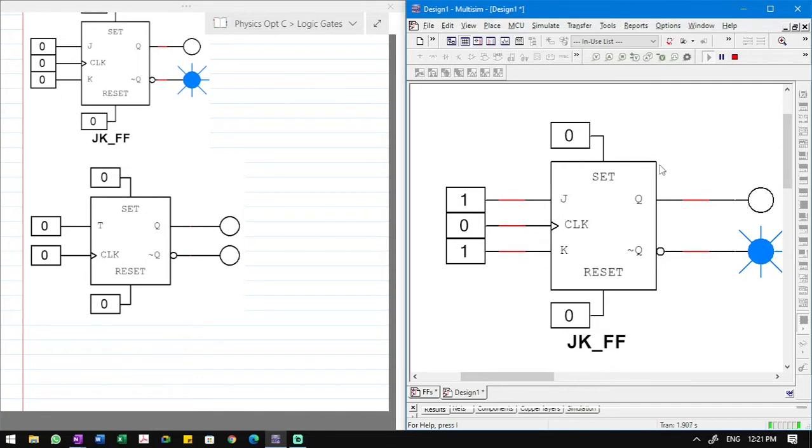Right. Now, as I was saying, in the JK flip-flop you cannot set up race conditions. Now it has an extra input here. So where you have S and R from before, that is now replaced with J and K, right? So forget about this reset and set above and below here, right? Those are separate.